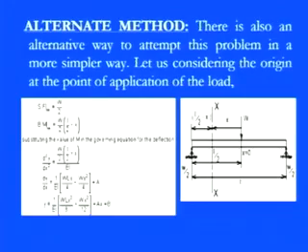It is a material property, as I told you first: E is the Young's modulus of elasticity, because whatever deflection is there, we already assumed it is elastic deflection, so stress is proportional to strain. So E is valid for these things, and I is the second moment of area, which depends on the cross section of the beam. If we have a rectangular cross section, we already discussed that it is BD cube by 12. With those things we can simply get d2y by dx square.